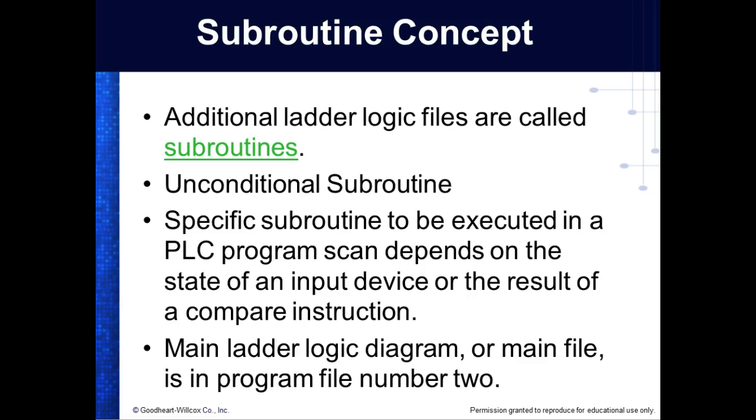What we do with subroutines is we call another ladder, completely separate. With jumps, we change the flow of the scan inside a single program. Jump to subroutine is when we call another ladder, so it's not contained within the main program.